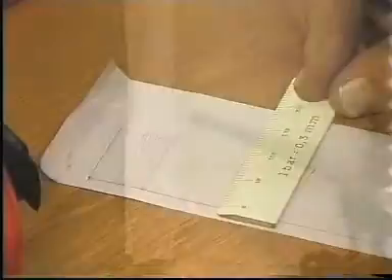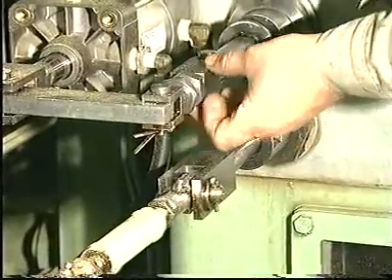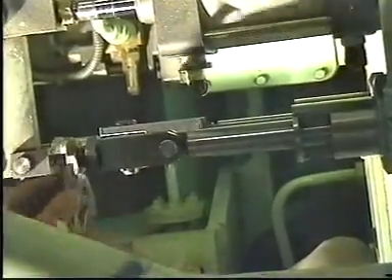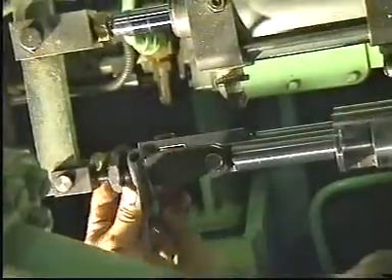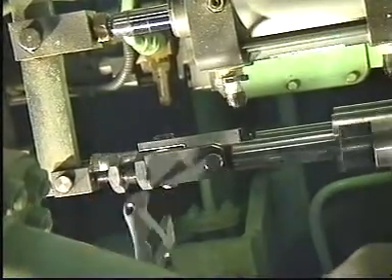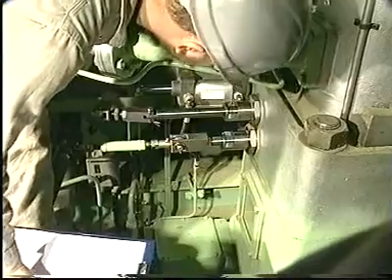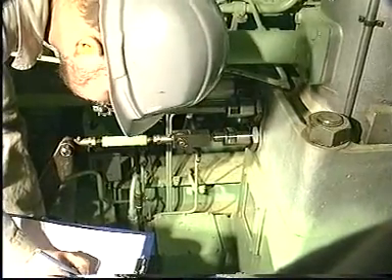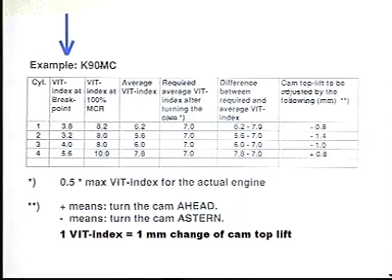Again, measure the maximum combustion pressures for each cylinder. Adjust the links or displace and lock the VIT racks so that the maximum combustion pressures, corrected to ISO ambient conditions, are uniform and have the required values. Note down the fuel pump and VIT indexes. Note down the VIT indexes at breakpoint and 100% MCR and calculate the average index.